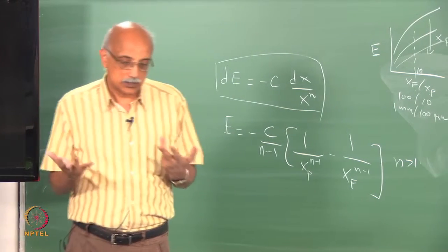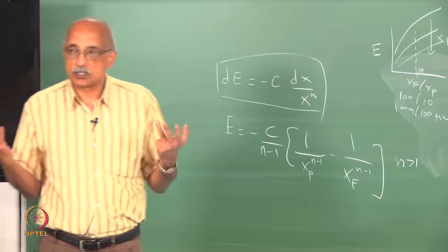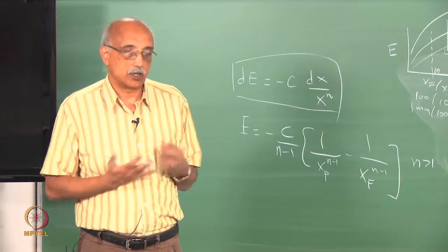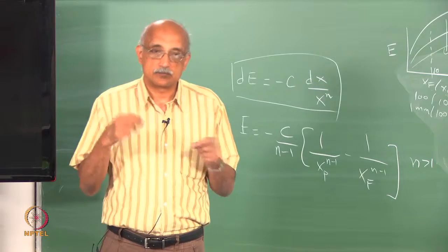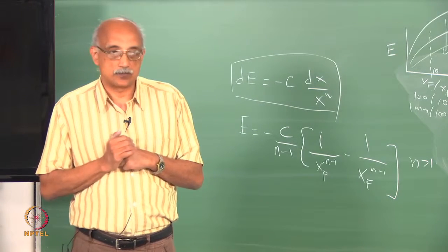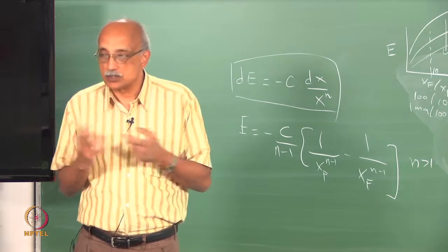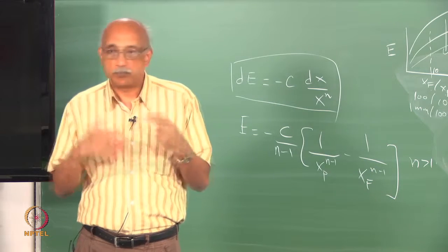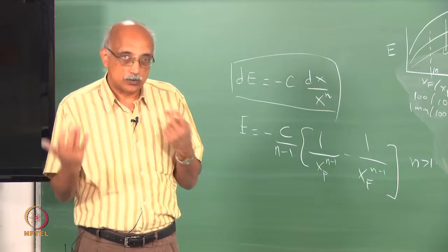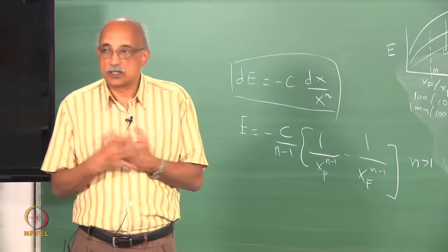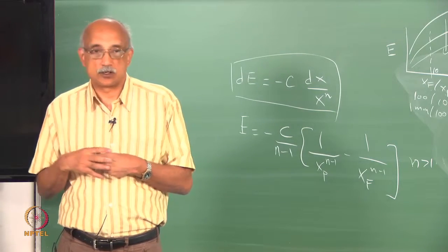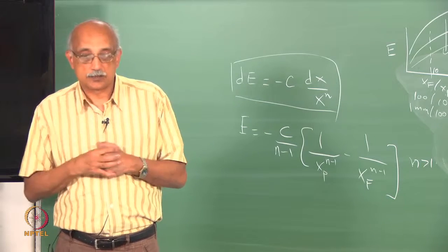If you look at industry, there are many types of size reduction equipment that are employed. In each of the categories that we have mentioned, you can subclassify them. For example, you have crushers, and there are impact crushers and roll crushers; or if you are talking about grinders, there are compression grinders, attritional grinders, and rotational grinders.